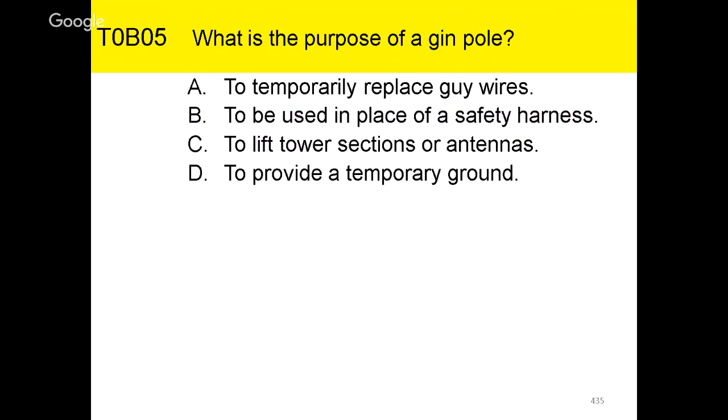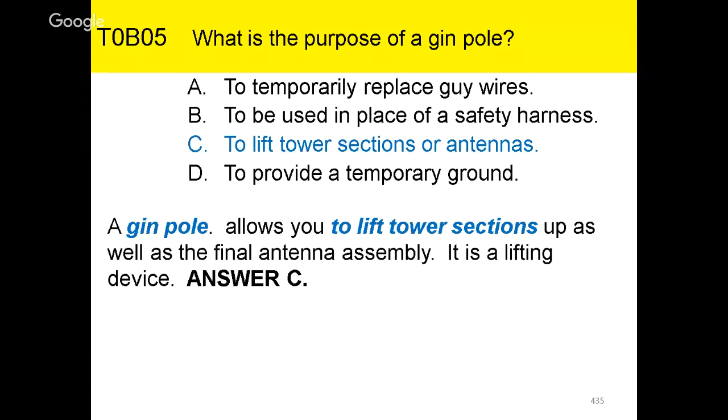So what is the purpose of a gin pole? Certainly not to mix your gin and tonic, or to play gin rummy or any of that other stuff. It is a simple little device that is used to lift your tower sections or antennas into place. The gin pole would strap onto the side of the tower piece that's already in place, and it extends